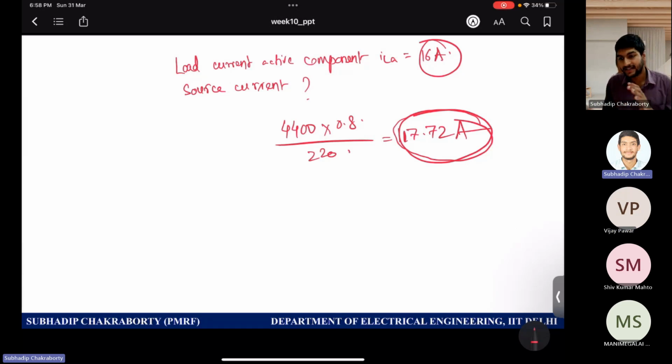So whenever for shunt you are calculating, do it in terms of currents; whenever for series you are calculating, do it in terms of voltages. But both things need to be balanced, because the processing is through the same DC link. Active power processing is to the same common DC link. So now the difference in current, let us calculate, that will be pushed to the shunt branch, the active current.